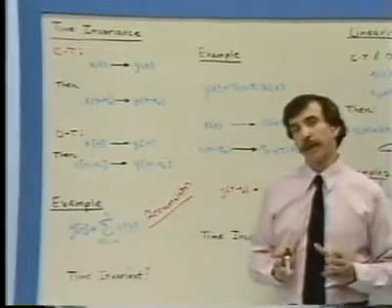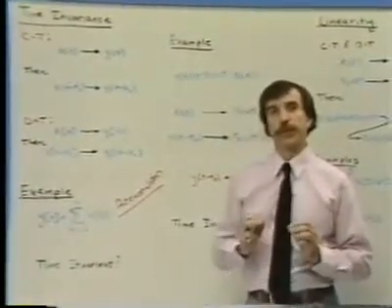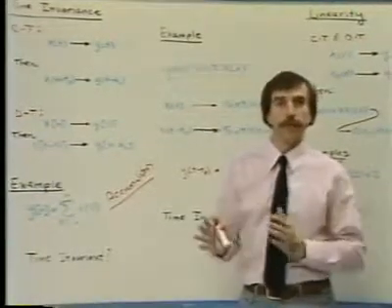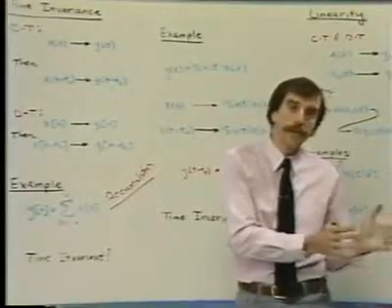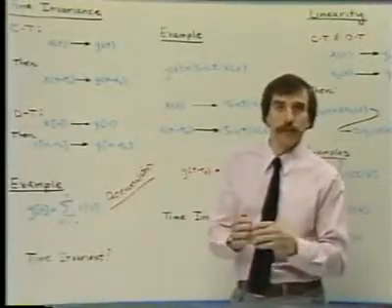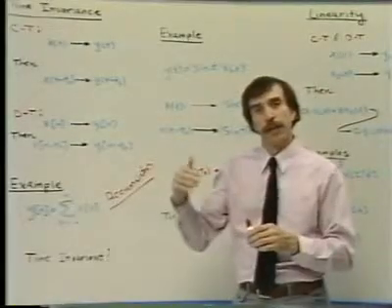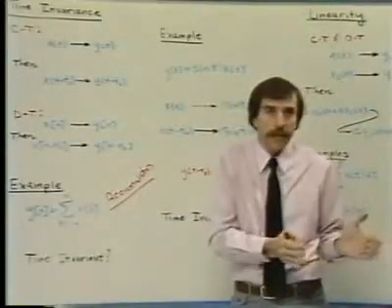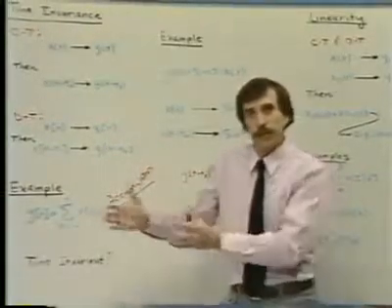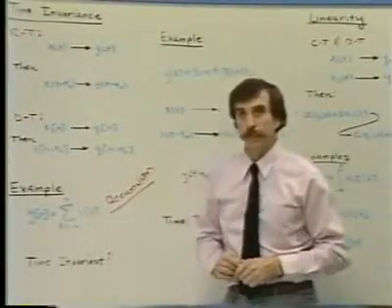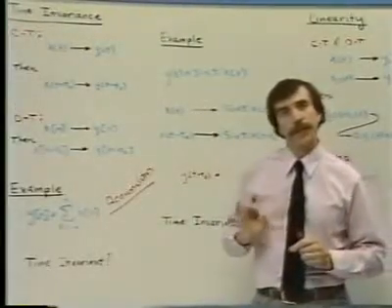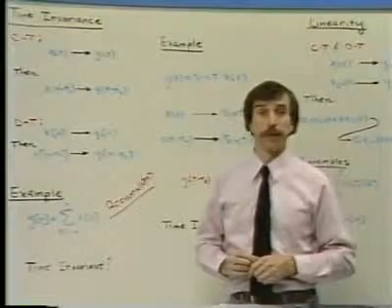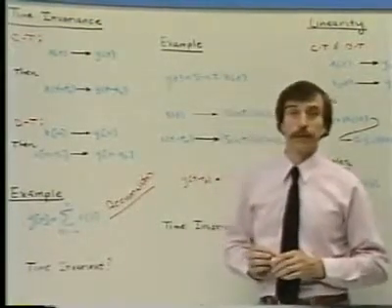Informally, if you think about it, it makes intuitive sense that the accumulator is time invariant, because if you're accumulating values and if you delay the values that you're putting into the accumulator, then the associated values that come out will be delayed by the same amount. The accumulator doesn't care really if you shift the input, it'll just simply shift the associated output. But more generally, if you're trying to test time invariance, it's important to return to the definition, and that's what you're required to do in the examples in the video manual.